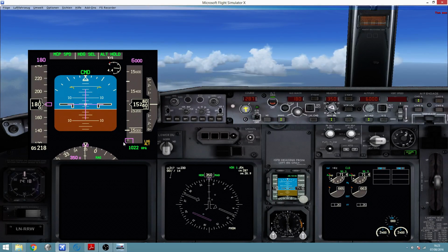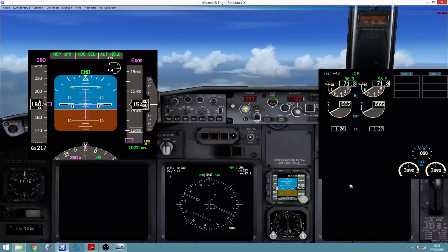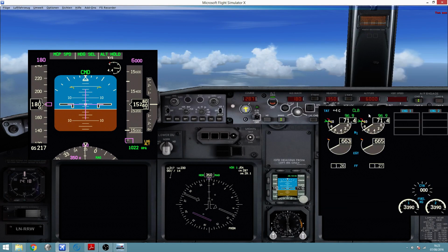The right pressure reference is set, and now I would just have to click on level change here on the MCP. What's this going to do? Since this is a descent, this is going to reduce the thrust of the aircraft that we can see here. These are the engines, these are the revolutions of the engine. It's going to decrease the thrust of the engines, and it's going to look for the selected speed of 180 knots with a proper pitch position.